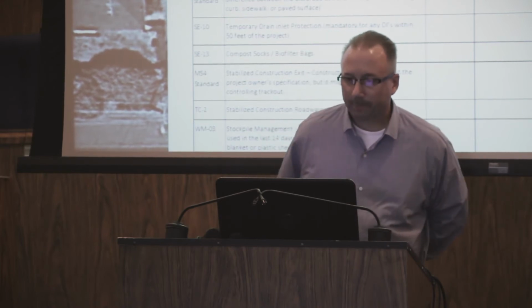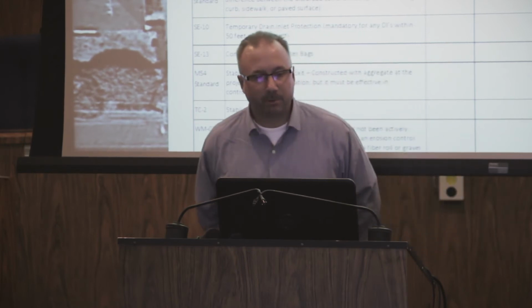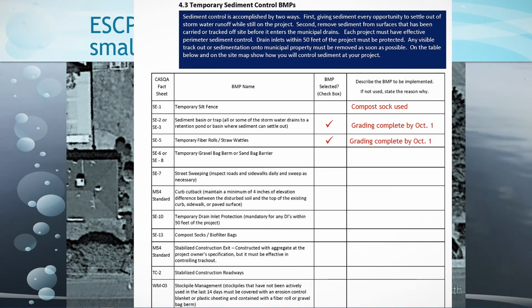The following one, SE5, temporary fiber rolls or straw wattles. Yes, we are going to use those in a couple limited spots. And when I say grading complete by October 1st, I'm also indicating that's when they're going to be installed. As soon as we're done with grading, we're going to install those devices. Next one, temporary gravel bag berm or sandbag berm. No, we're not going to use that.